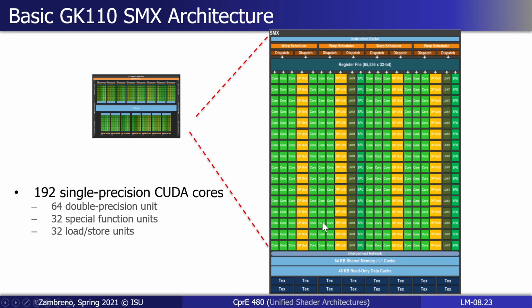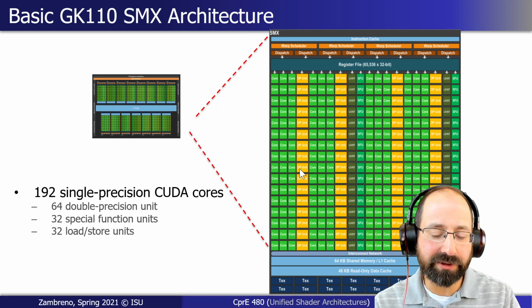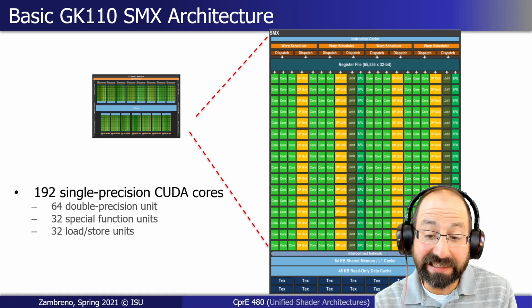From our perspective, in our implementation, everything is fixed point units, so we don't really play around with that trade-off very much in this class. I've certainly thought about it. What would be the downside of having all of our hardware be floating point hardware in this class? There are some advantages to floating point hardware, right? For single precision, everything is a 32-bit piece of hardware. That's a nice thing.